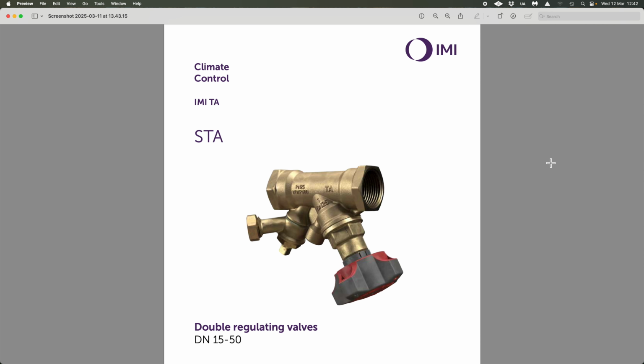So apart from temperature control that we need to work out, and of course if the water main is not buried correctly in installation terms, that temperature will fluctuate even through the day because it's too close to the surface air temperature. This will have a detrimental effect on the efficiency of the boiler when trying to set it up on the hot water side. But the other point that we have is pressure and flow rate.